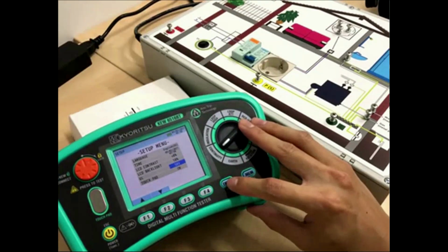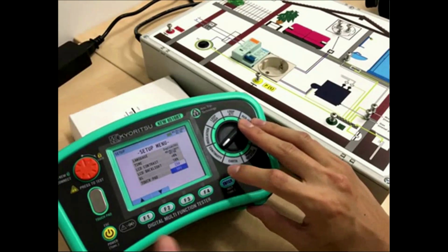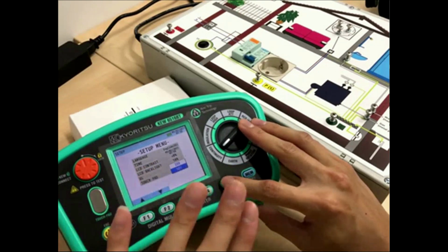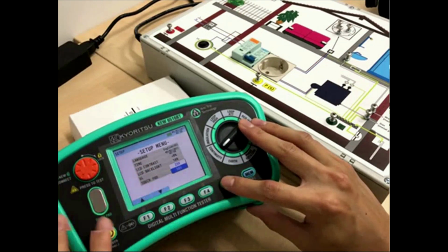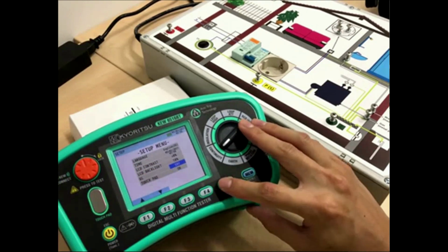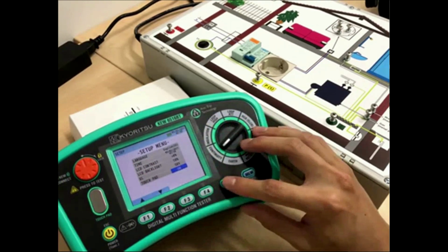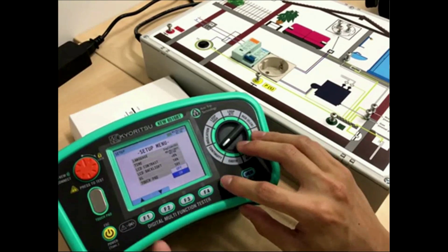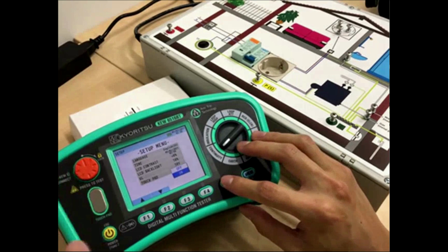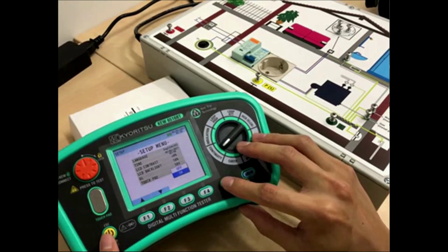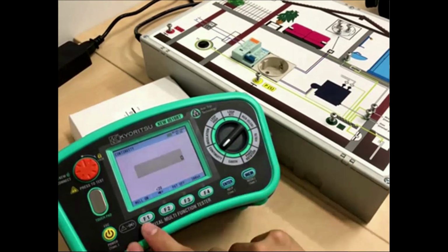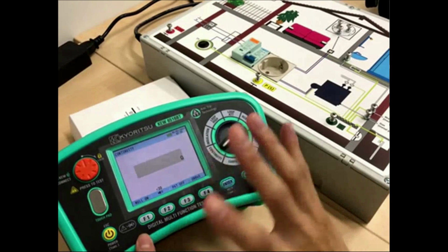This is to set the safety touch voltage. Enter. There is 25 volt and 50 volt. This one I explained to you already just now. One is for general use, one is for construction site use. Touchpad: what is the touchpad? If you turn it off, the touchpad will not be used. Now we leave it on, enter. Then we go back.